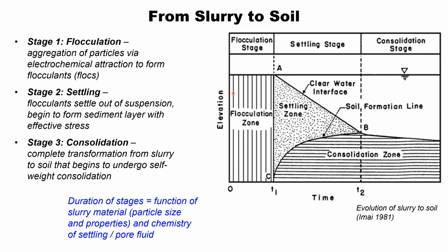And so this is plotted both in terms of time and here as elevation. As the material moves farther inboard or upstream, we're going to get a zone where settlement occurs, where we start seeing settling of those particles, and then a zone where we start to get consolidation under a certain amount of additional weight of those particles settling down.